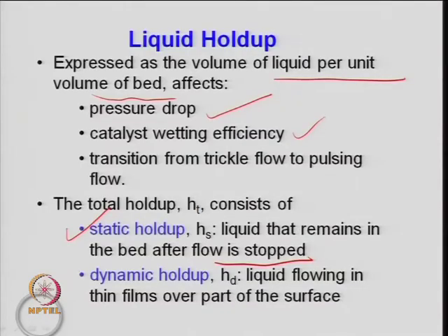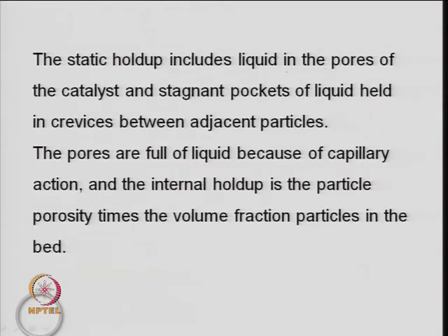That will be the static liquid hold up. When you have a continuous flow, the liquid is flowing in thin films over the surface. Whatever liquid you have at that time, the volume of liquid inside the bed, is your dynamic liquid hold up, the volume of liquid under running condition. Static liquid hold up includes the volume of liquid in the pores of the catalyst and the stagnant pockets of the liquid. So, the catalyst is already saturated.